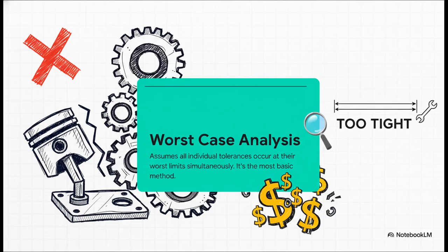Now, this method is totally bulletproof. It guarantees your assembly will fit every single time. The big downside? It often forces you into specifying incredibly tight and therefore incredibly expensive tolerances.